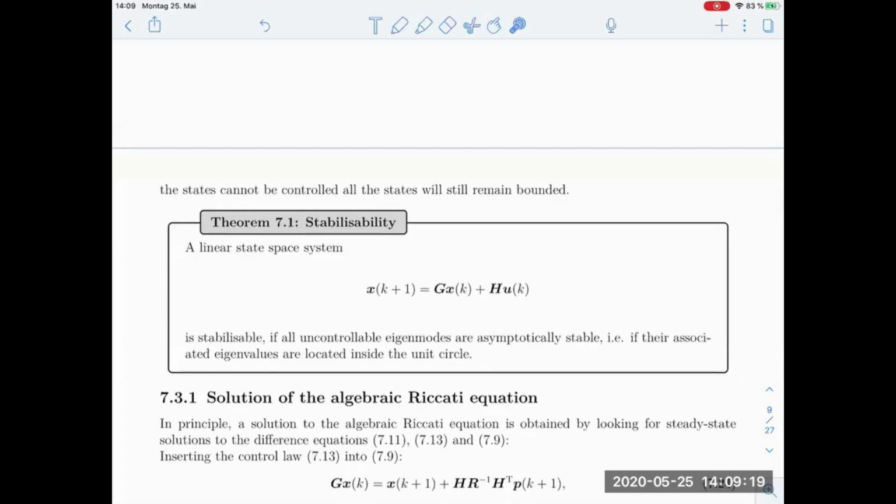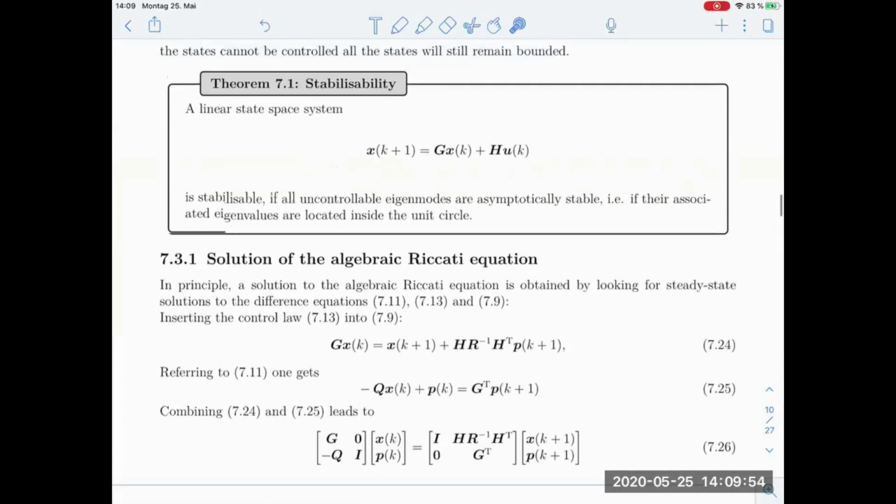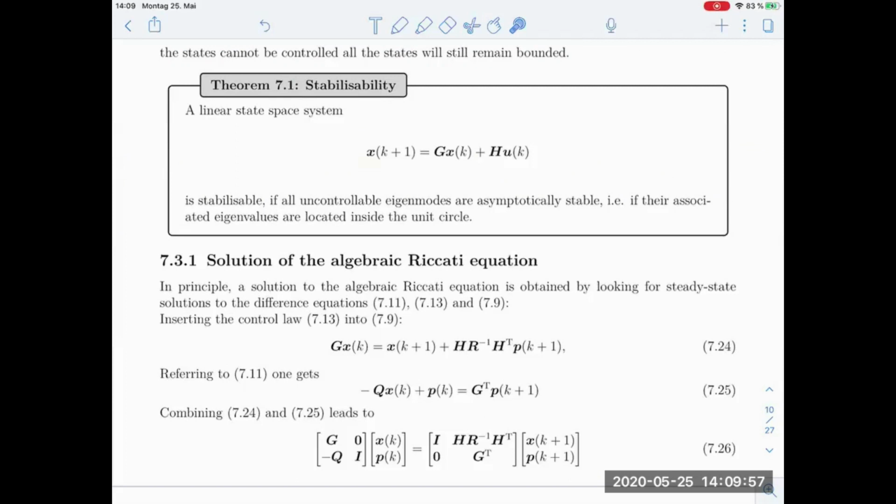All right, now how can we solve this algebraic Riccati equation, which is a polynomial equation, a higher order equation in a matrix? It's already not easily possible, it's more involved than solving it in a scalar fashion. Gladly here we get to a quadratic form, so we can solve a scalar quadratic equation in that sense. We'll do that afterwards to look at the weightings. But for the matrix case, that is not so obvious. So let's see how we can get to a solution to actually solve the algebraic Riccati equation.